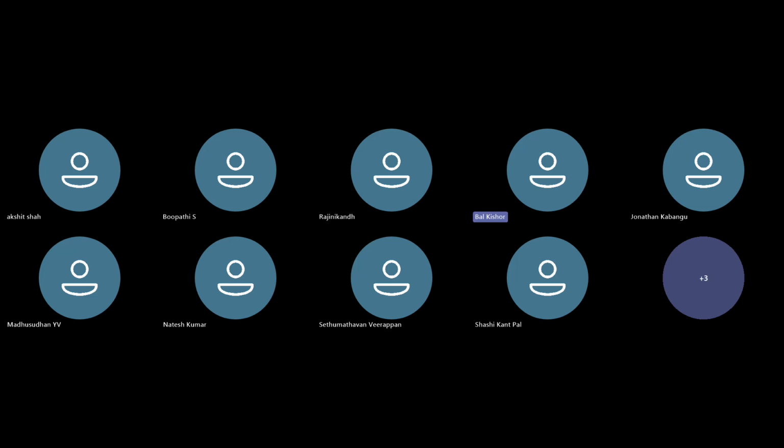I also told you this is not giving you a very clear idea of which node voltage is the blue color and which one is the red color. So instead of that, you can name those nets. So go there or press N for net label and put it like V in, press OK. And this one you have to connect. Wherever you place, it will get connected.